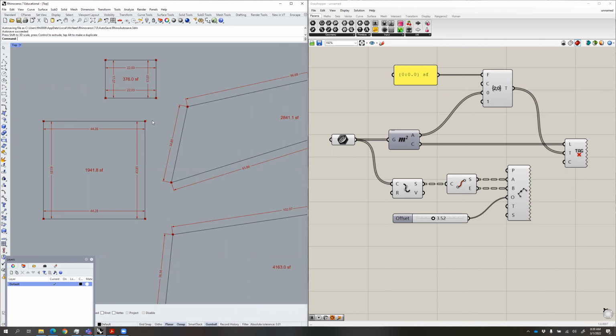I appreciate it whenever you guys ask these good questions, because then I can tell you things that I probably would miss as I go through this. You basically just need to take these pieces of geometry and flip the orientation. So if I click the geometry in Rhino and type in flip, that basically flips the orientation of it. And so that fixes that.